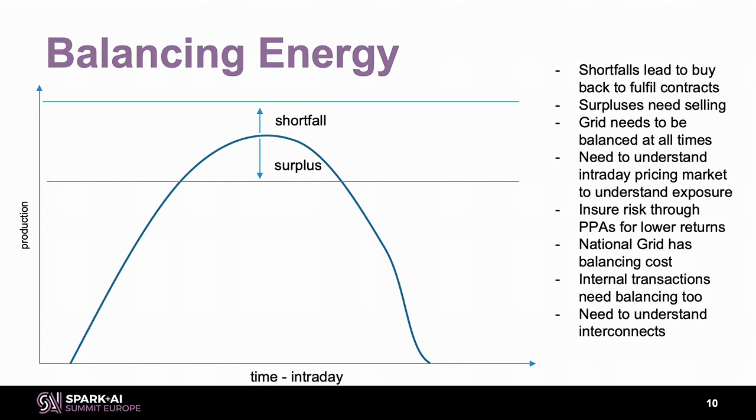So it gets much more complicated than this as well, because the grid itself has to balance. Right? Our national grid has to cover demand, it has to cover supply, and these two things have to be equal at any short point in time. So the grid will also use tariffs to stop you from putting too much energy in at a point in time, and it can say, well, actually, we're going to charge you like £20 if you want to put this energy in. Right? And of course, you're going to lose money then if you put this in. So there's all of these different things.